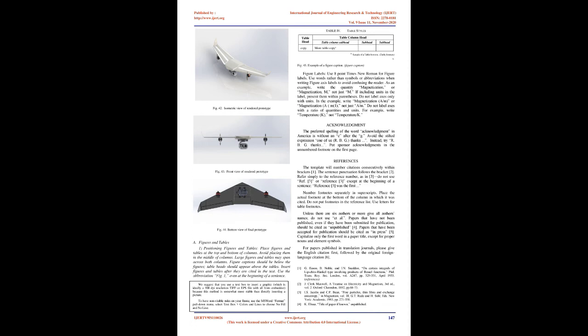During egress from the water body, the wing has to propel out at a high velocity and the spoilerons are opened to drain out the water, making it lighter for aerial flight. The spoilerons are then closed once the UAV enters aerial flight. Fig. 39 and Fig. 40 show a sectional view of the active ballast for ingress.